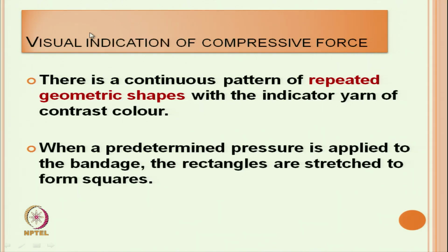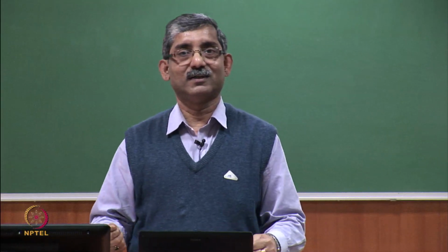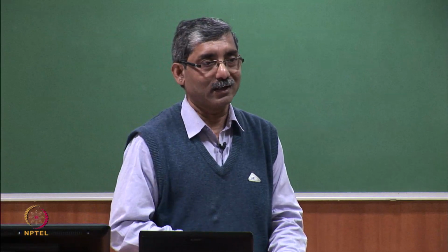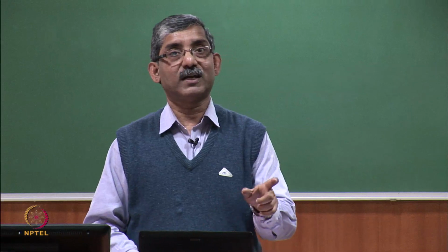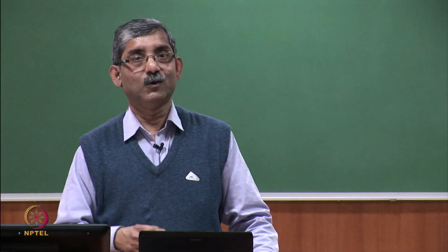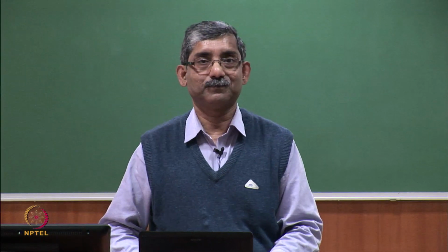Another measurement technique here, which is a very simple one: the bandage is actually printed with a geometrical shape. Depending on the tension and stretch, the shape will change. Like, the geometrical shape is say a square, and depending on the stretch it will become a rectangle. So, from there, if we know the stress strain characteristics, we can predict the amount of pressure it is applying.